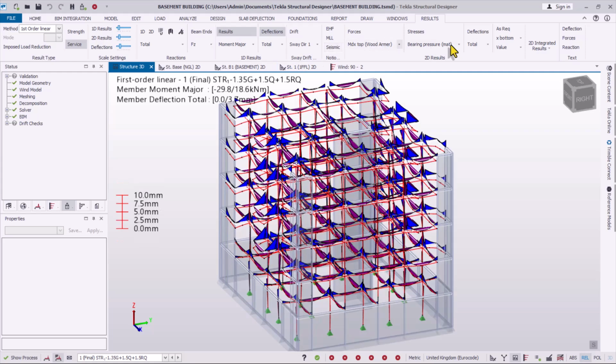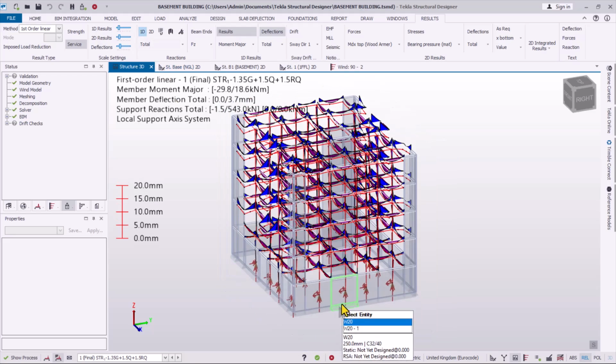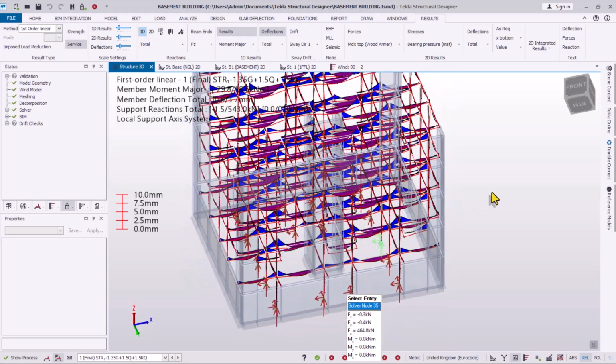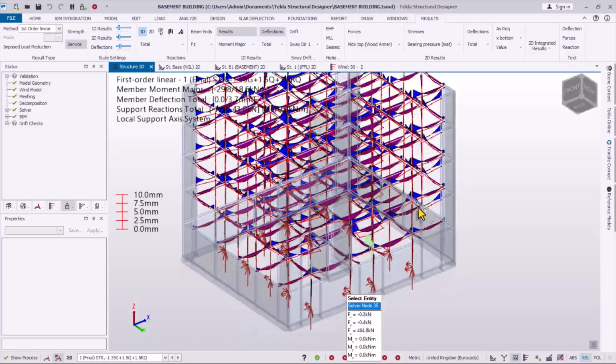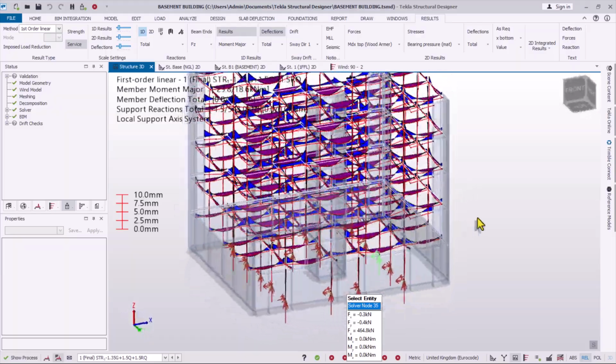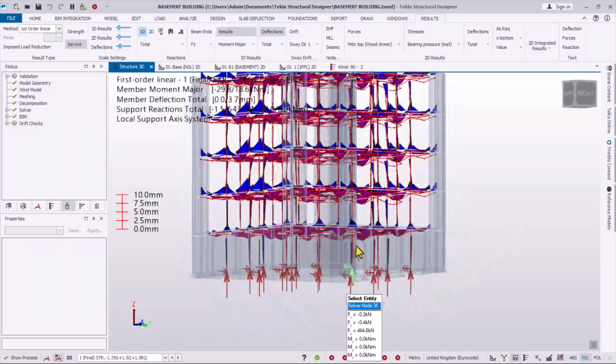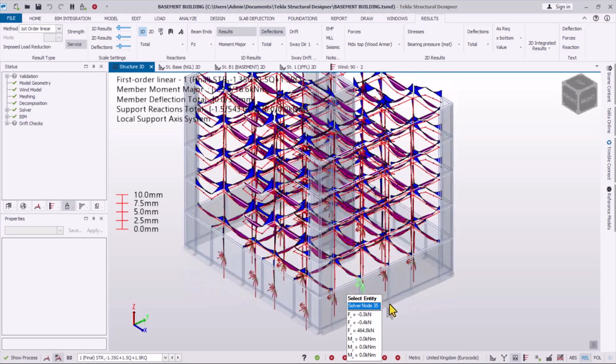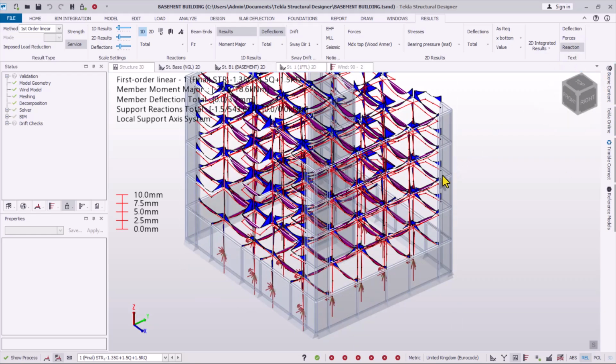You can check other things that you wish to check, like the forces, okay? But for now, we can look at the reactions. If you click on this ID right here, you will notice that we have some reaction lines on the reinforced concrete column, but not on the walls. Now if you click on the reaction right here, you can see the reactions.